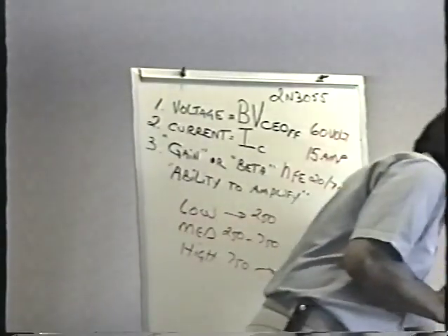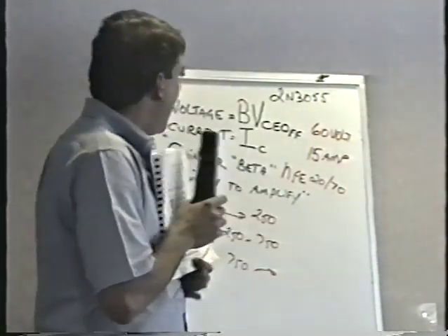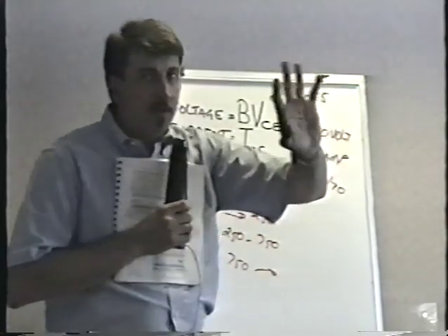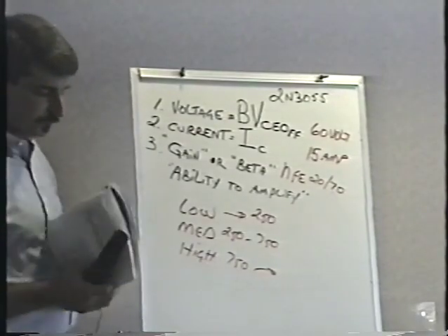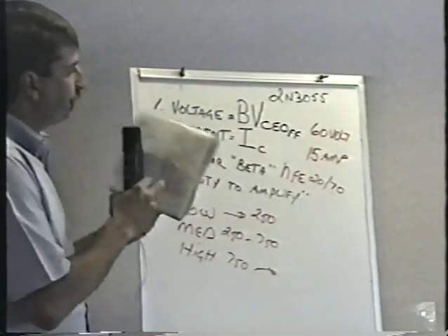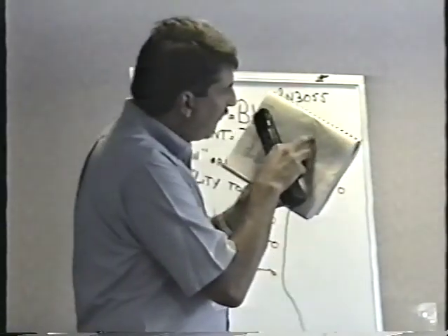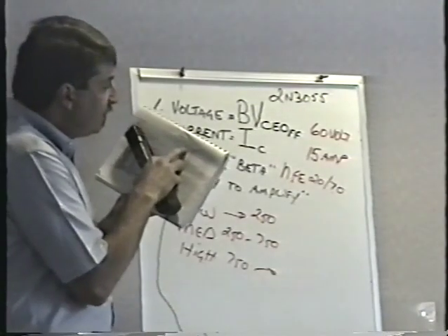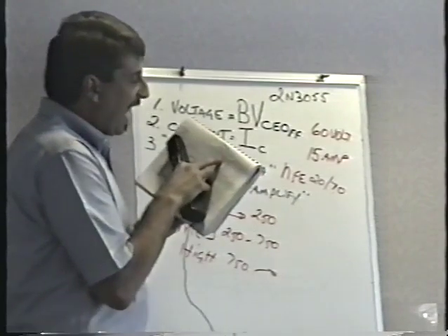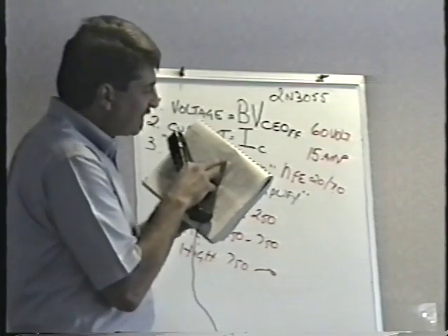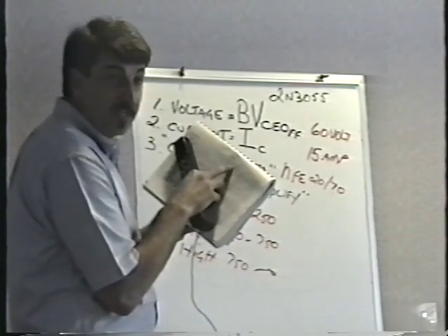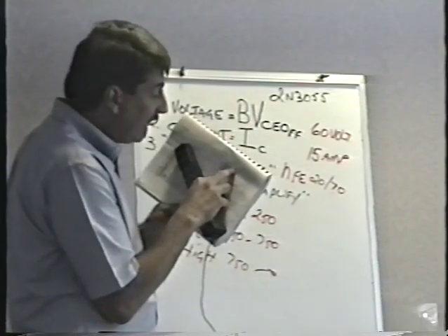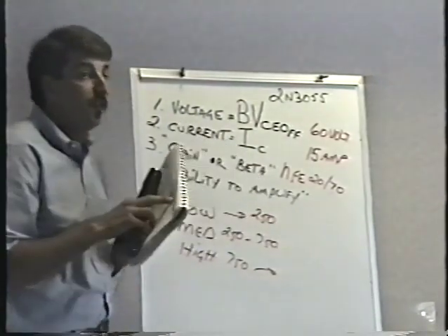So let's take a look at some of these transistors. Let's say that we have a bad 2N3055, 60 volt, 15 amp, low gain, right? We got a bad one, and we need to get a substitute. Look in your chart here on page R-7. Right underneath the 2N3055, find this 2N5881. Could I use that as a substitute? Yes. Absolutely. Look, the I sub C, the collector current, 15 amps, voltage 60 volts. That's exactly the same. The current gain, the H sub FE, the beta, 20 to 100. Definitely, it's almost exactly the same transistor.